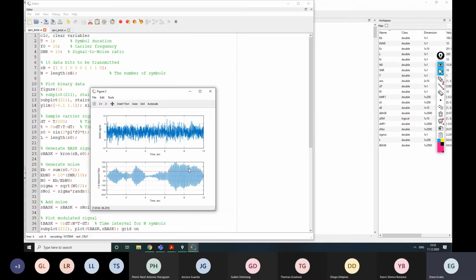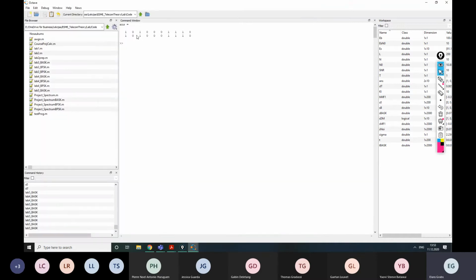So here we can see not so easy to understand signal, but nonetheless, the approach is still the same. We read the value at the end of each symbol, and compare it with a threshold. Right? And that's how detecting is performed. And still, as you can see, there are no errors here.